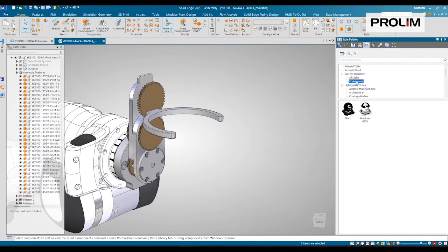So initially, if we're going through and filtering down several thousand parts to find two or three surfaces that we need in the model, we can quickly capture those here if we need to reuse them later on down the road, and we don't need to filter through all of those thousands of parts. So let's go ahead and take that aluminum 6061 now and just drag and drop it and apply it to the glass holder.